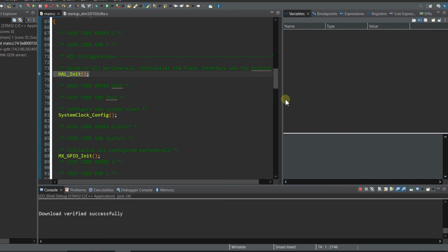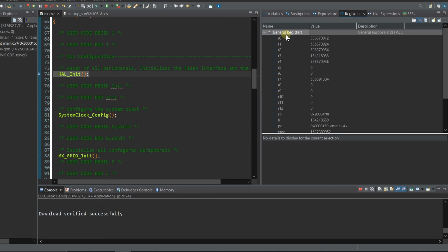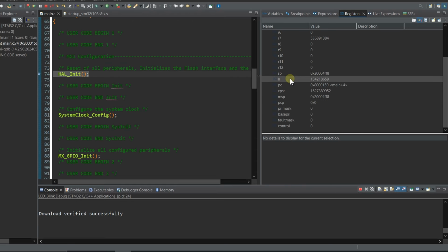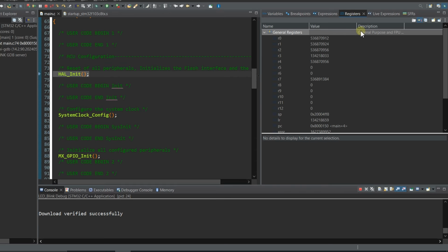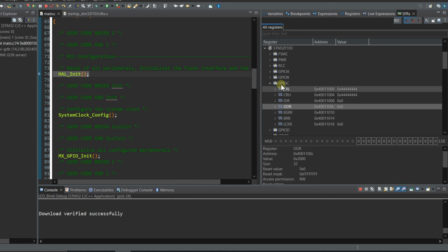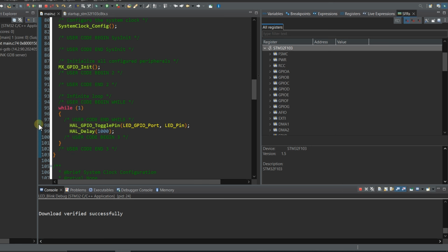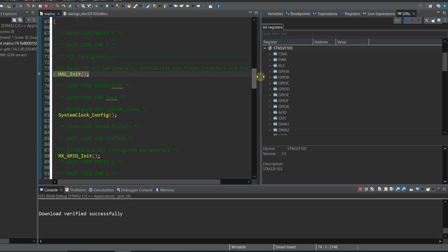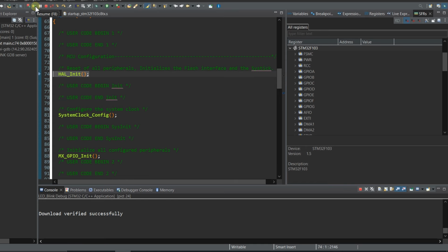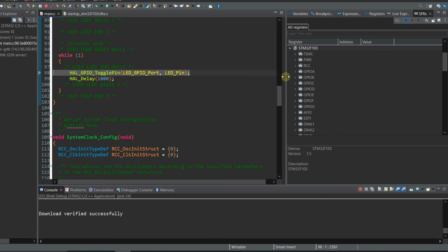These are the processor core registers. There is also a window like this one showing the core registers and peripheral registers. I'll double click and set a breakpoint. I'll run execution until the breakpoint. The PC13 LED is currently off.